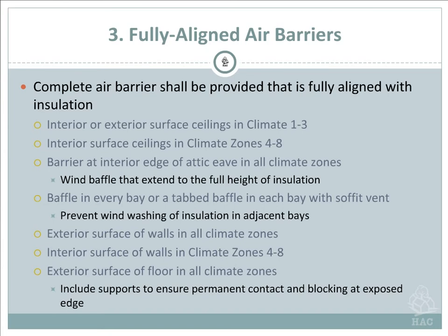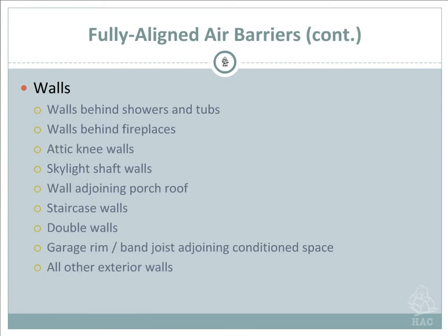Again, you want to prevent washing of the insulation into adjacent bays, and we'll talk about this. This is why you want the baffles in there, okay? So all the exterior walls and so on in climates 4 to 8 need to have these baffles. I want to show you. Again, we'll talk about all the different walls.